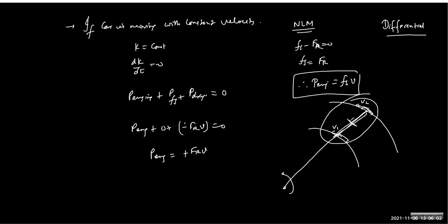We have a cut here, and you will see there is a round box at the rear, and this will have a gear system. So both gears can turn at different omega and achieve the turning. While the car turns, the two wheels must move with different velocity to achieve the same omega. So this is called a differential.